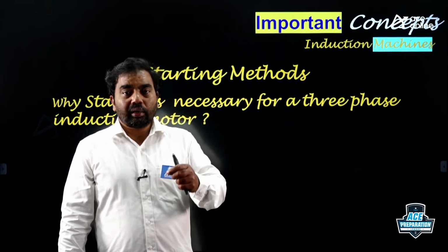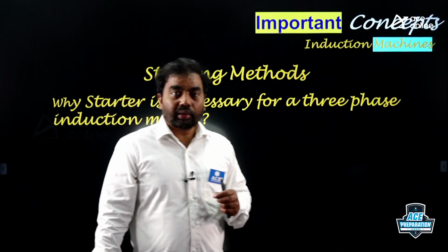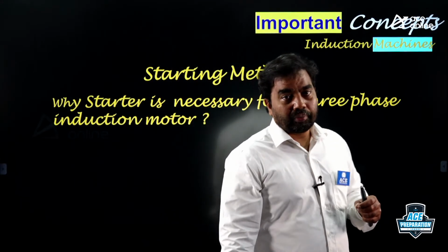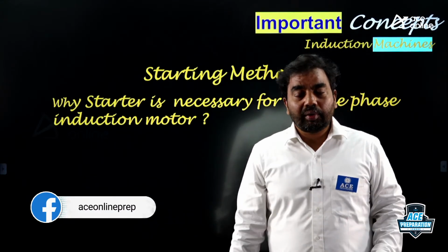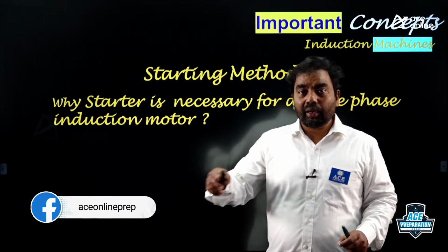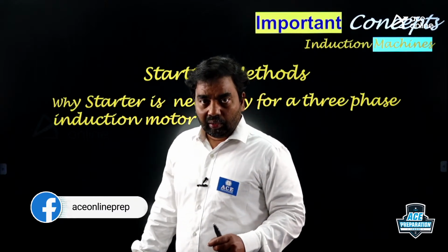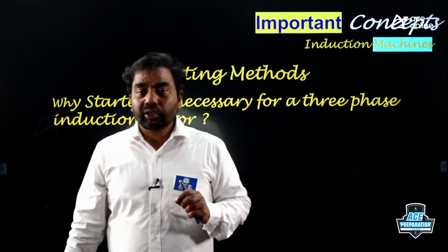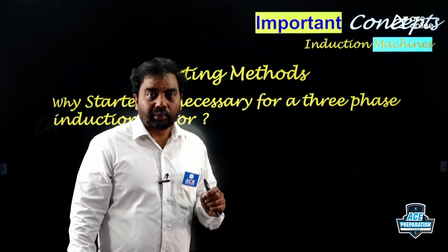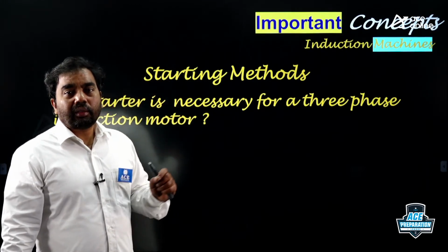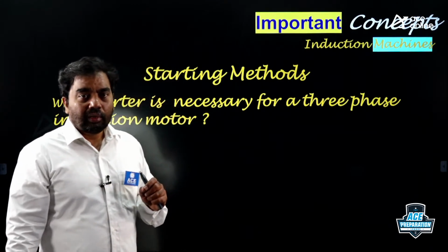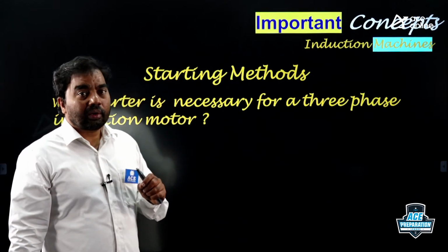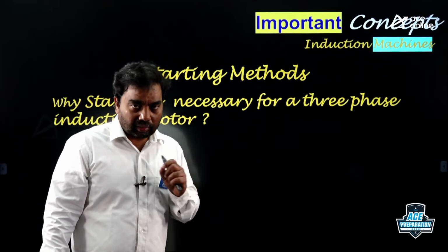Because of these induced rotor currents, there will be one more field, that is the rotor field. The stator field and the rotor field will interact and they make the rotor rotate. So finally, a three-phase induction motor is a self-starting motor. But why it still needs a starter is, as the name says, not for starting the motor, but to limit the high starting currents.